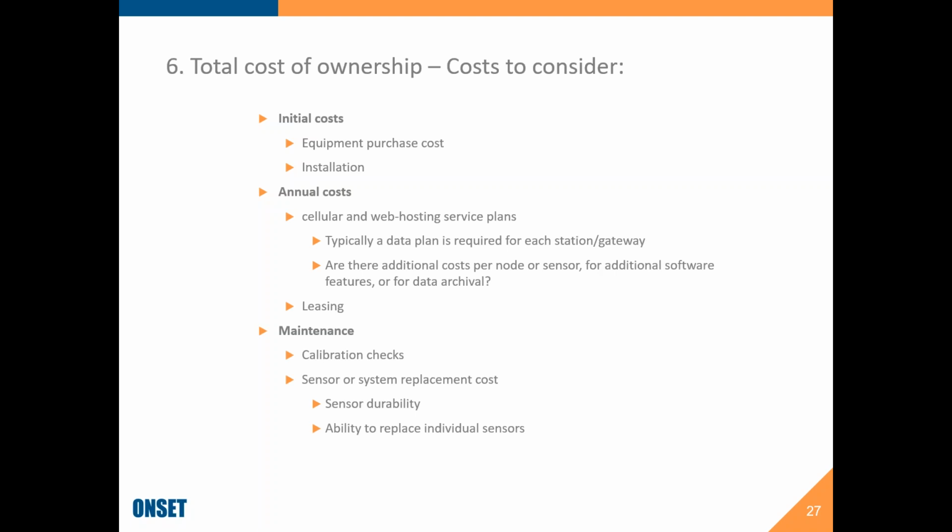Then beyond the annual dollar costs, you need to factor in the maintenance costs. It's a good idea to get out and check your systems at least once a year, make sure that sensors are still accurate and reporting reliably. If you need to replace sensors, it's nice to have a system which you can replace just the sensors that you need to replace, rather than having to replace the whole system. So look for that kind of modular serviceability.